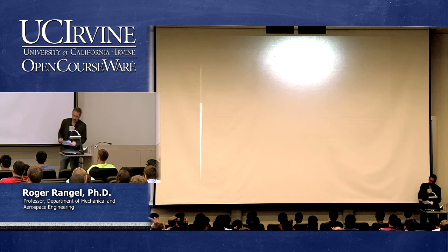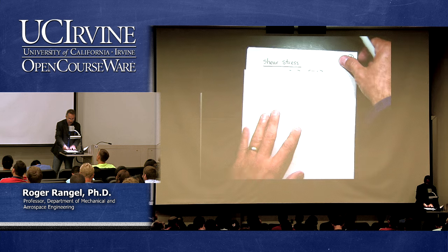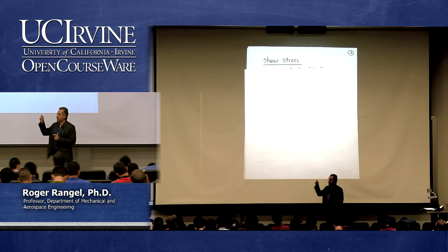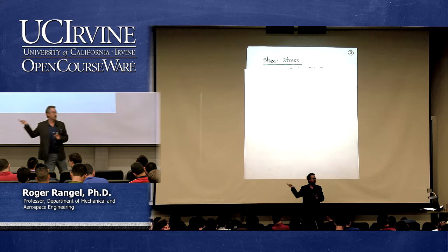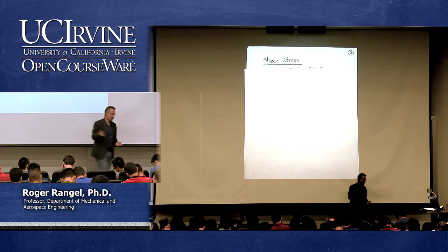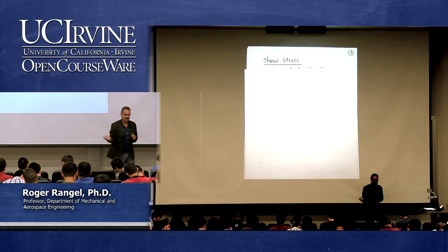So let's go back now to the shear stress. You were thinking about Pascal. This is now shear stress. Do not confuse shear strain rate, which is what we just measured, with the shear stress that we were talking about at the beginning of the lecture, which is the force per unit area. Two different things, but they're going to be connected now.